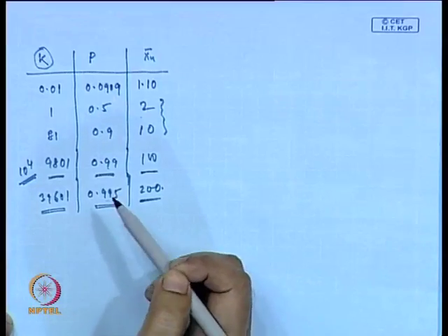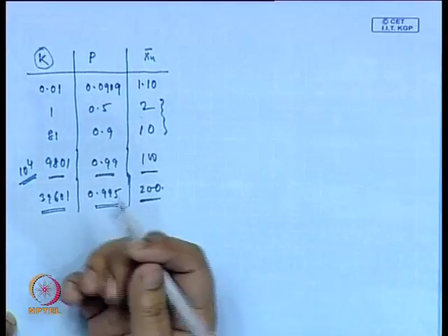So, this convinces us that there is no other way, we have to do a reaction where we always continuously take out the condensate from the system. Now, what happens if we take out the condensate, the products will move towards the right hand side. So, polymer will build, but it is almost impossible for engineering design to take out every possible condensate, all the 100%, in this case H2O for a polyesterification reaction, for so many reasons.